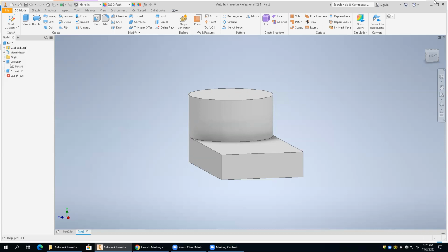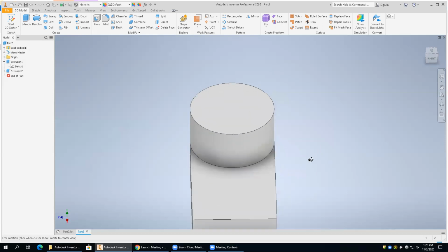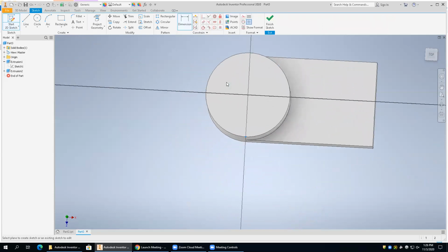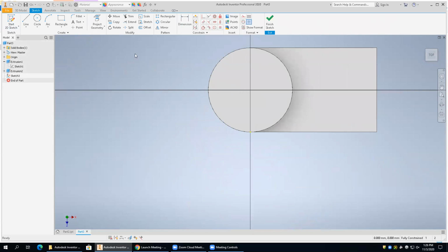All right, so we're gonna generate a circle on the top of this and drill a hole down through the bottom, okay? So get to a view so that you can make sure you can just see the top of that cylinder. I'm gonna do a 2D sketch, select my circle. Now it should pick up automatically. If you just come here, it should actually jump right to the center. So just hit that and then drag that out. Don't worry about the diameter of it because we're going to place it at a value. Okay.